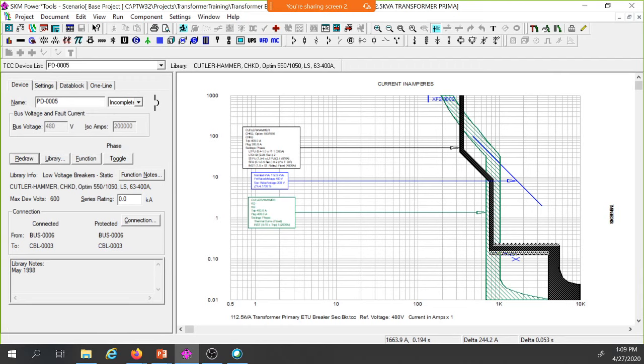You just want to stay above that. So, I could put this down and it may not trip, and it may trip at a future time that I energize that transformer. You just want to keep it above that inrush, because that's a data point that we have based upon standards for that equipment. And then I can modify this curve, and I am to the left of that transformer damage curve. And this would let the transformer energize, and I don't have to worry about selectively coordinating the secondary with the primary.